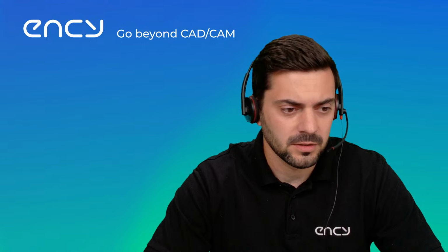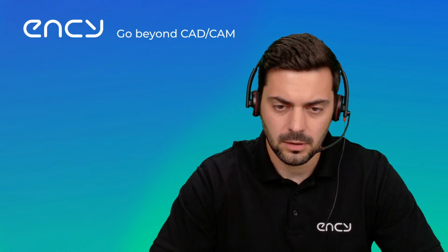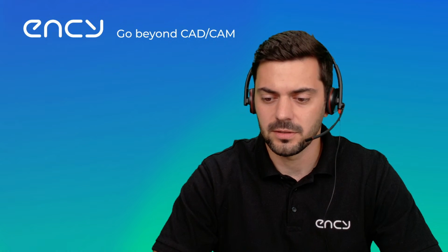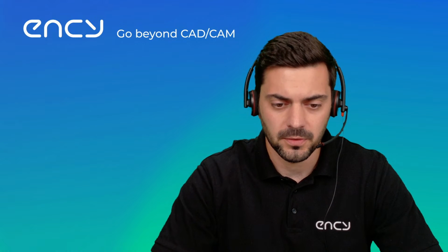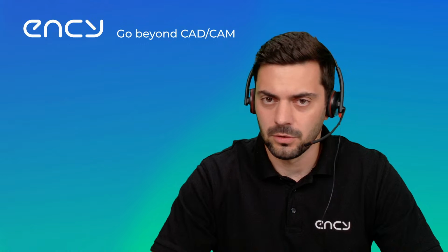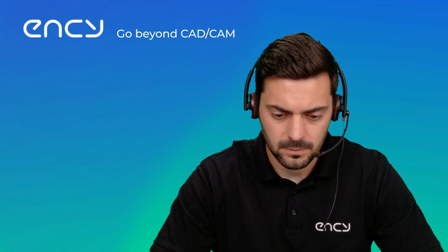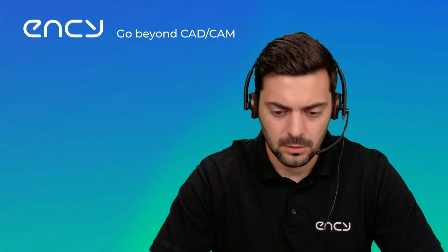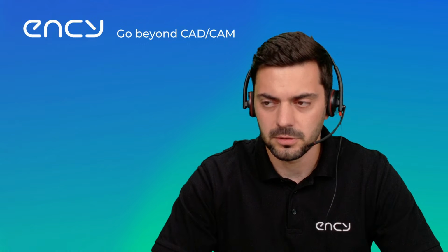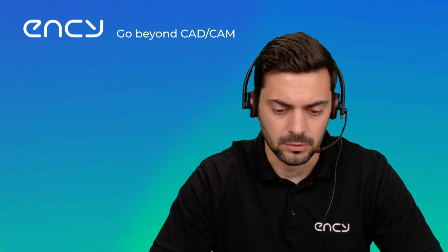The behavior of this redundant axis is not defined in the ENCY code, and you have to create rules for this additional axis on top of ENCY code. This is the functionality of ENCY Robot. You cannot do this in ENCY Tuner. So technically, it's better to use full ENCY Robot for generation of programs for robots, not ENCY Tuner.